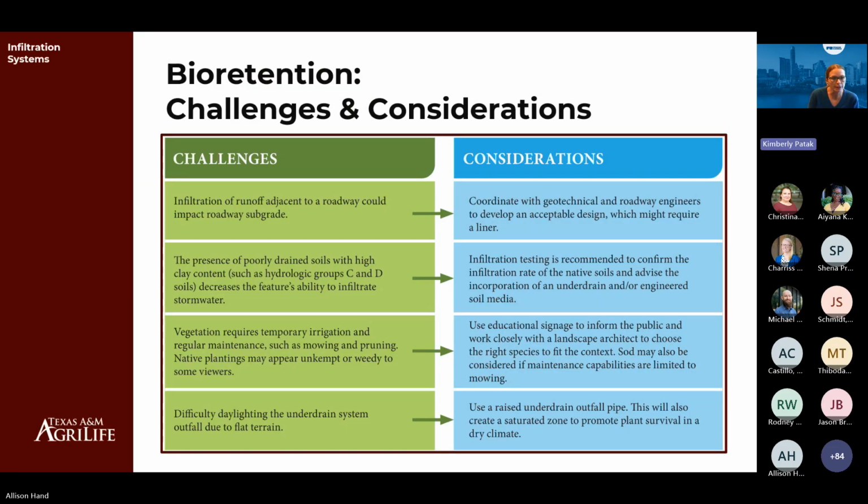So we've highlighted a couple of the typical challenges that people have in implementing a bioretention facility. Like all infiltration designs, it's critical to perform infiltration testing during design and post-construction. So you want to make sure that you safeguard that underdrain system, and even perch that underdrain system to allow natural infiltration, but continue to have an underdrain there just in case.